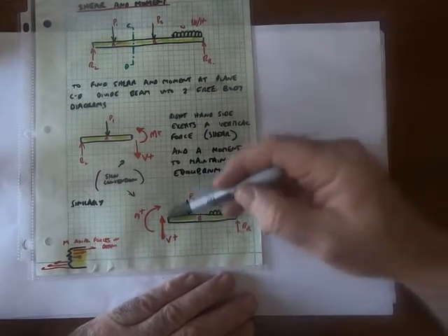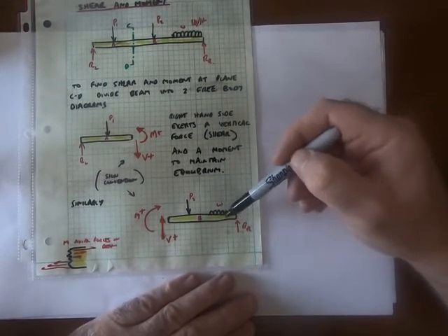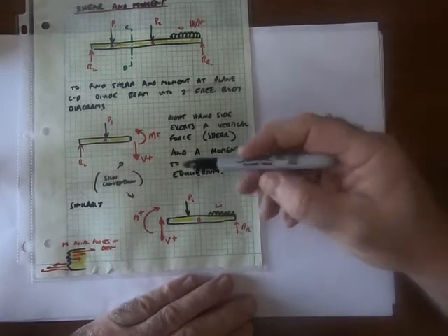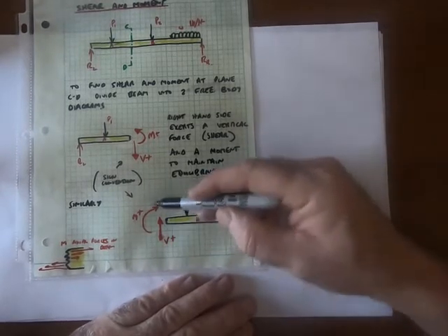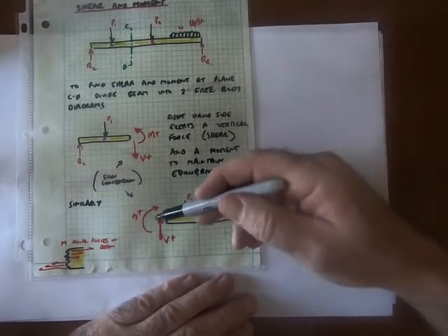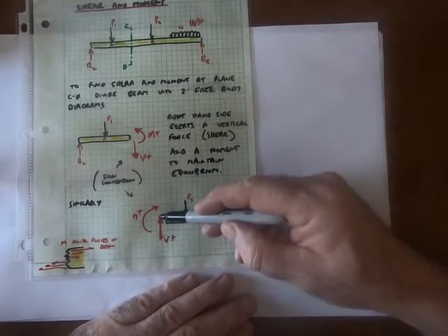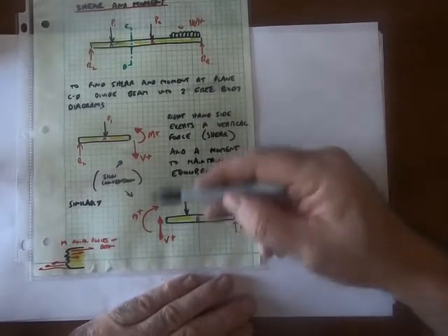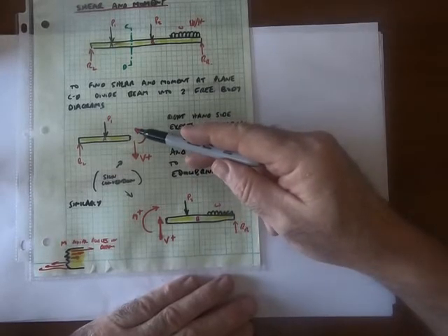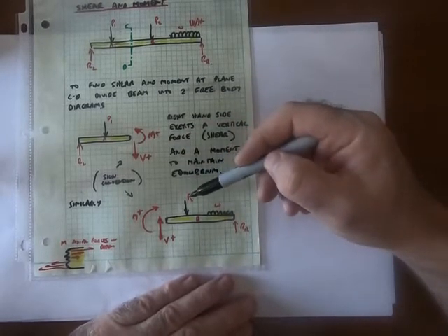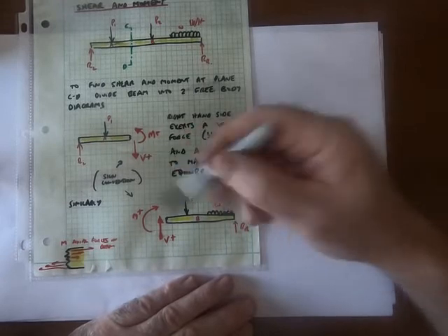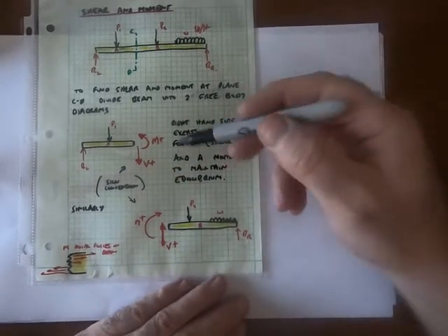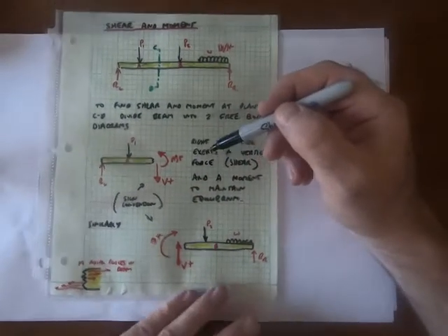We have this beam that now has to be supported because we've cut it effectively. We would have to provide a shear force and a moment, and convention is, when we go from right to left, that the shear force is positive up and the moment is positive clockwise. Obviously they're equal and opposite to what we found on the left hand side, because that's what we need for equilibrium. Newton's second law, equal and opposite. So, anyway, moving on,